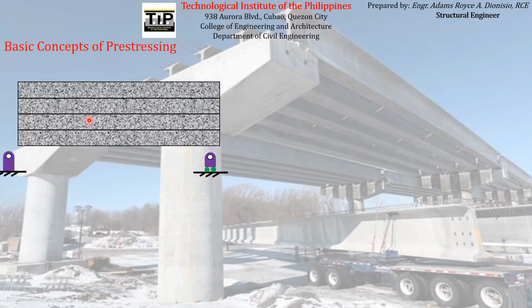And say for example, our concrete beam is just simply supported, and say for example, we have put a pre-stressing reinforcement along the centroid of the cross-section of the concrete beam. And due to this pre-stressing reinforcement, a compressive force is being applied to the concrete beam.